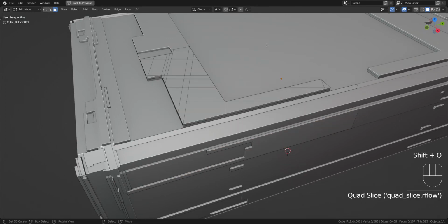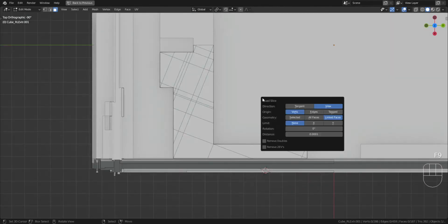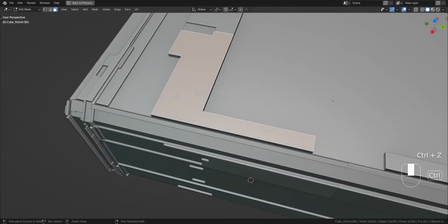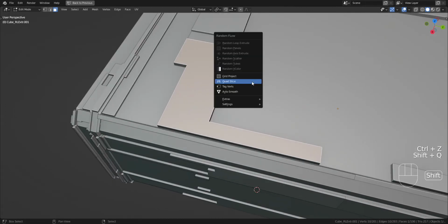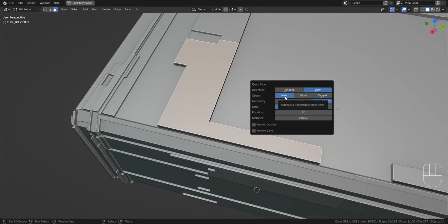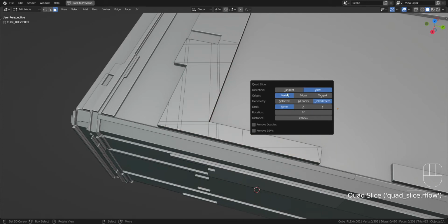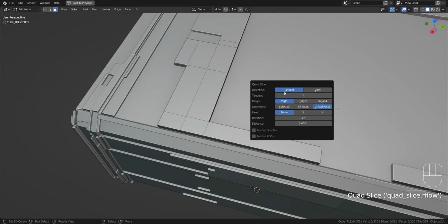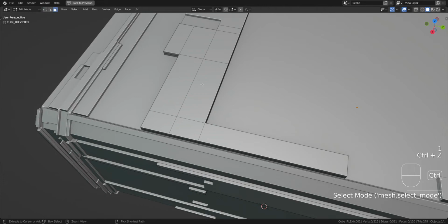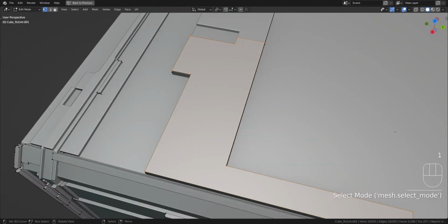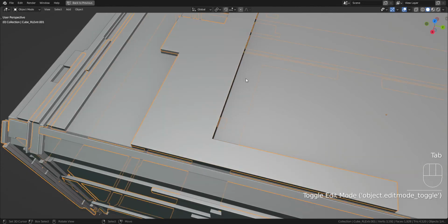Okay, so view, but if we change the view to here and press view again, then we have this. So verts, the origin, verts, which means that the cuts will be sourced or will originate from the vertices of the selected face.